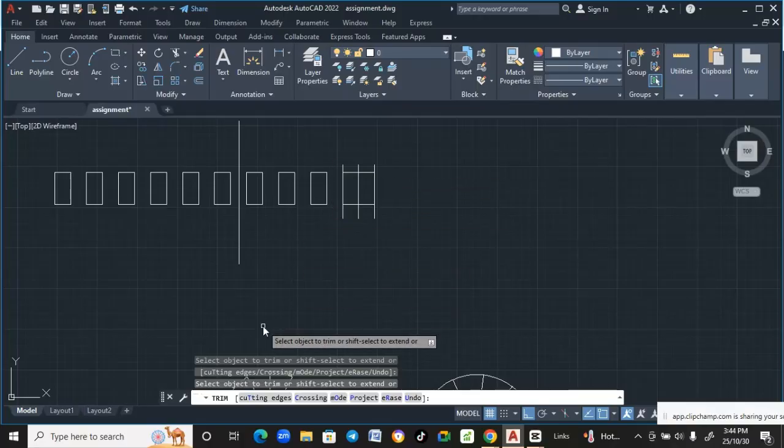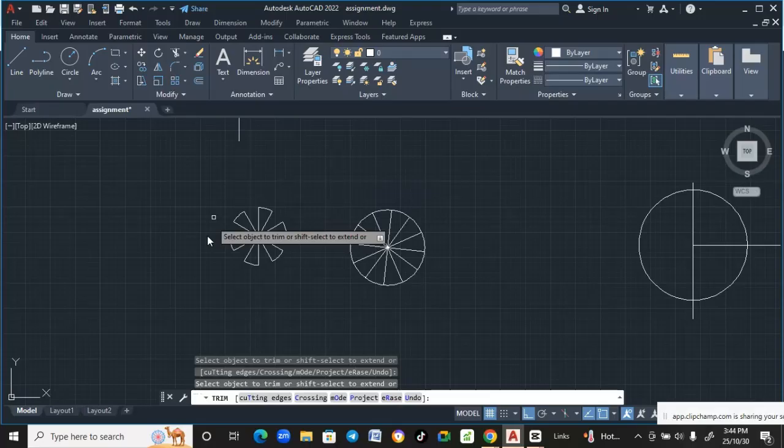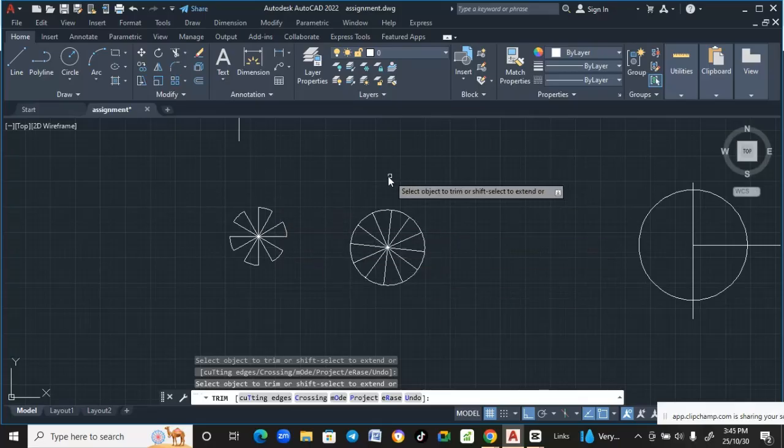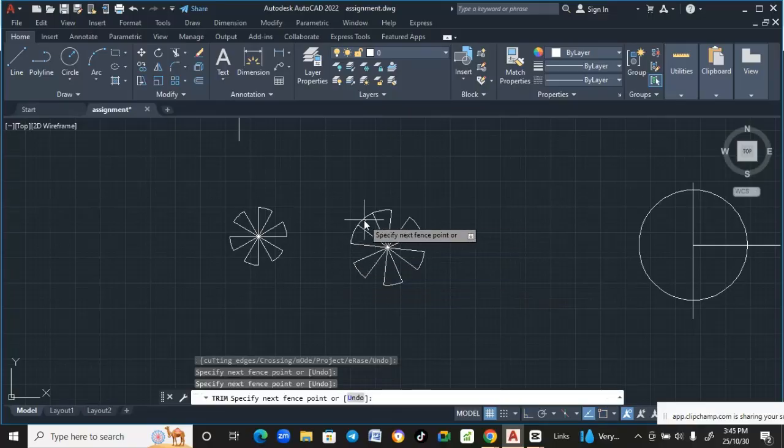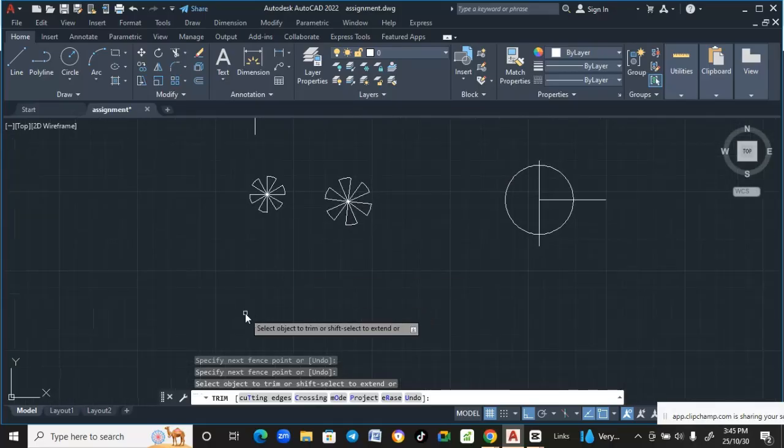Now here, how do I create this? I just created a circle and divided the circle. This has six parts, so I just divide it into 12. How do I do it? I now clean out alternate parts, using the same trim, trim them out, and you have this. Draw a circle, divide it into 12, and then trim out alternate parts.